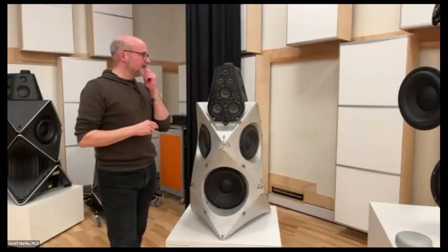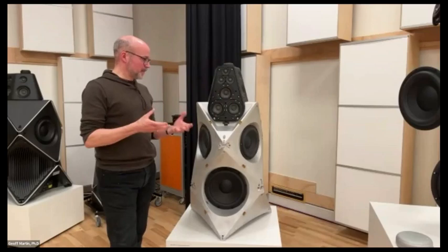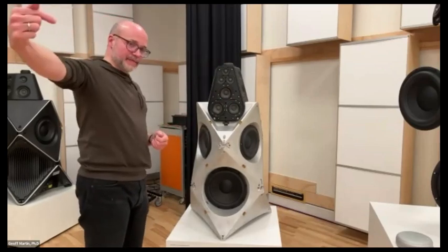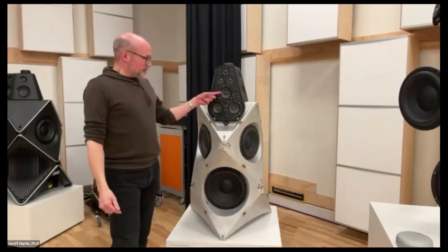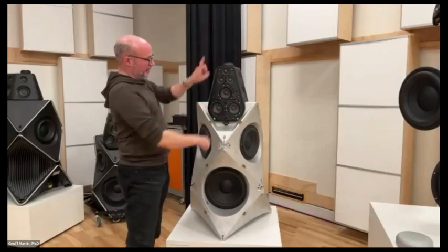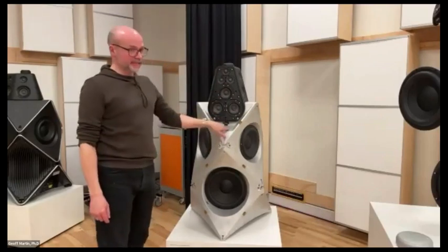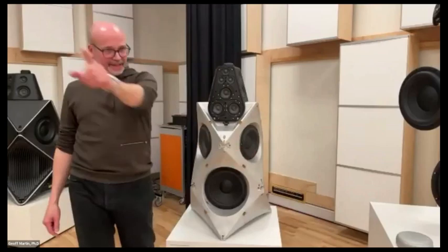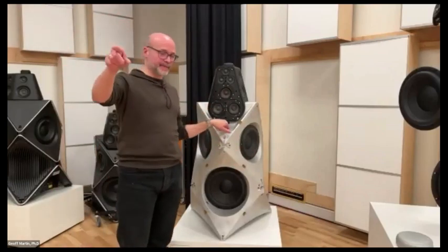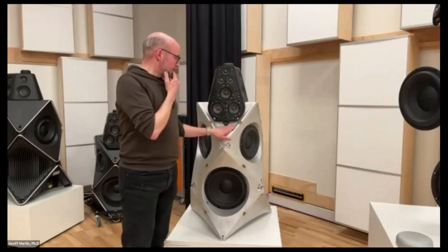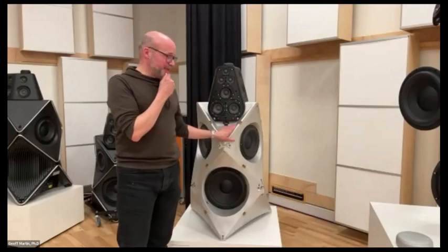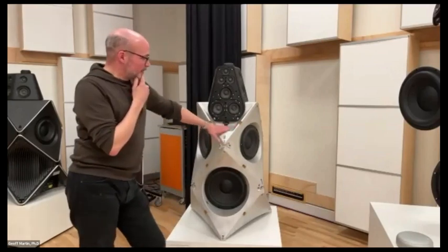And it took us a long time to find out what was causing that. In the end, what we found out was that at least at 3 meters out, this driver radiates outwards, of course, but it also radiates vertically. And when it does radiate vertically, it hits this shelf, bounces, that gets out to the microphone, and that will cancel this at 800 hertz by about a dB. That was a problem for us. It was a bigger problem for procurement because we wanted this to go away.